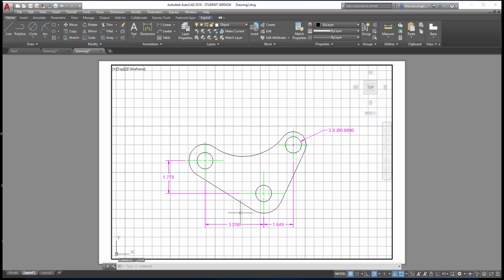All right, well, that should pretty much take care of how to create a basic geometric construction and how to get it into a layout to plot to PDF, for you to create either a printed drawing by choosing a different printer, or a PDF environment.